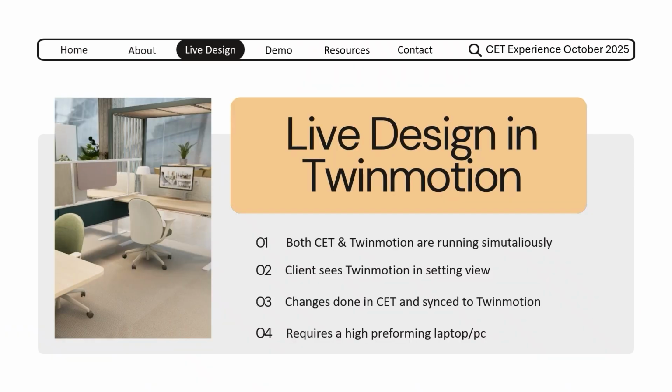You can also do live design in Twinmotion. You're still going to keep the practical tips from what we just spoke about, but there are going to be 4 other key aspects. With this version, you're going to have both CET and Twinmotion running simultaneously. The client preferably will only see the Twinmotion view, and all the changes that you do in CET, you sync up with Twinmotion using that direct link. However, this is more demanding on your computer, so you do need a high-performing laptop or PC.